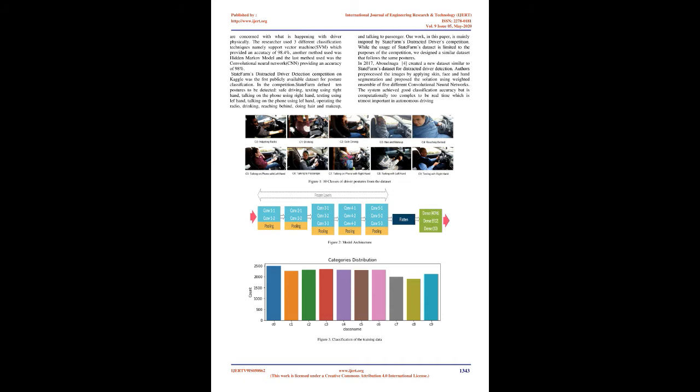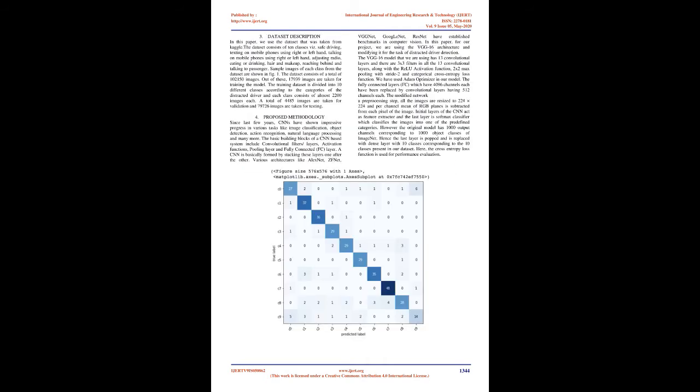They use the percentage of eye closure ratio, and based on the result of the ratio, the eyes are referred to as open or closed. Yawning-based detection systems analyze the variations in the geometric shape of the mouth of drowsy drivers such as wider opening of mouth, lip position, etc.